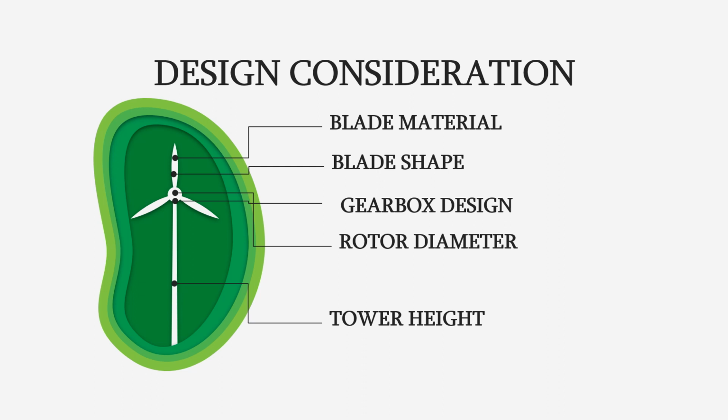Blades are typically designed to have a curved shape aerofoil that generates lift as wind passes over the blade. There are many different blade shapes available, including flat, curved, and twisted designs. Some designs may be more suited for specific wind conditions, while others may be more suitable for particular type of turbines. Number of blades. The number of blades can also affect the efficiency of wind turbines.